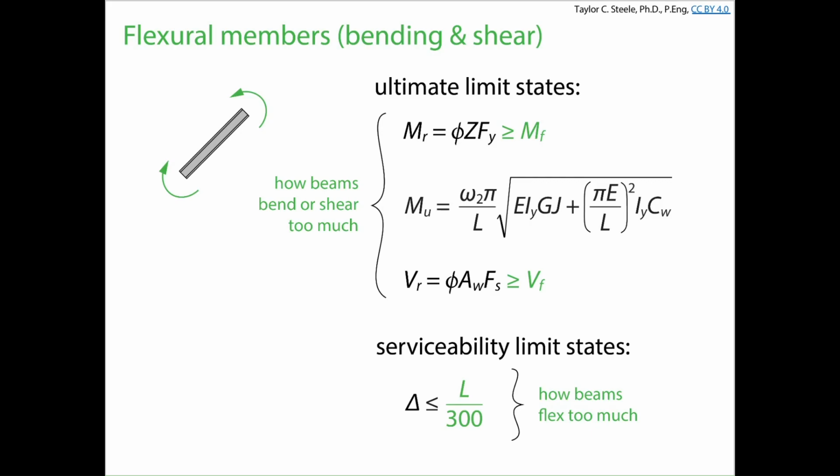Last day we looked at the shear resistance of our webs, of our I shapes. We're really focusing on I shapes as beams because 95% of the time we're using a wide flange section. And they could either fully plastify, experience inelastic buckling under shear, or elastic buckling under shear, and it all depended on how thin the web was relative to its height. Today we're going to start talking about how flexible beams are and how we need to limit deflections to prevent cracking of certain components of steel structures.